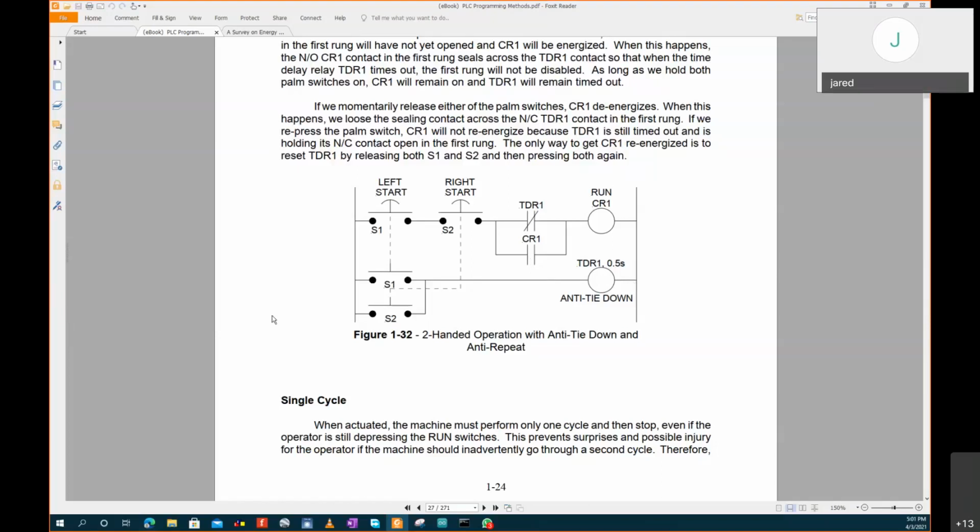And in this upper rung, so this is the first rung, okay? So you press this, you get this first rung on, but before the timer elapses, this becomes on. This is what supplies the power. But before this timer is done, there's no power. So if this timer is already out, if you press this switch, because there's no circuit completion here, nothing will work.